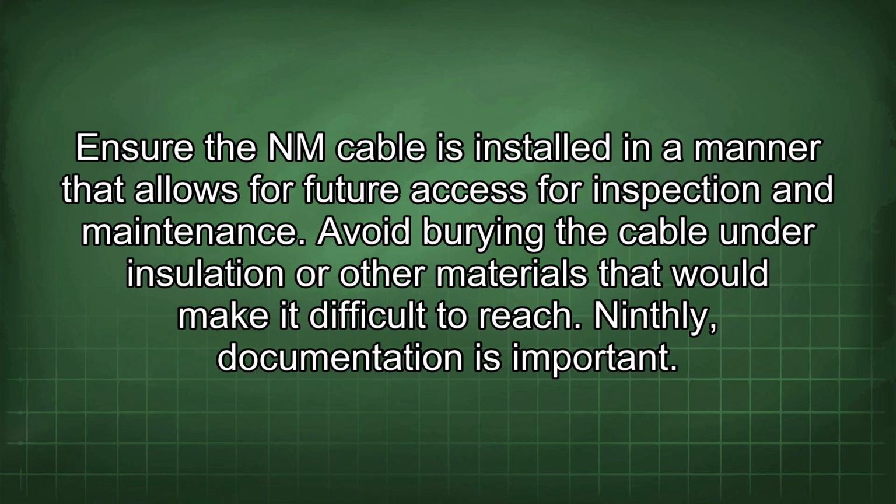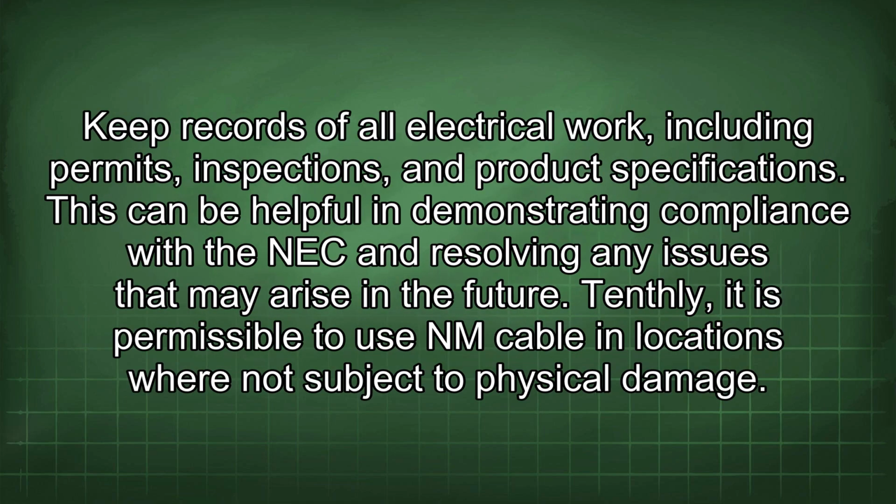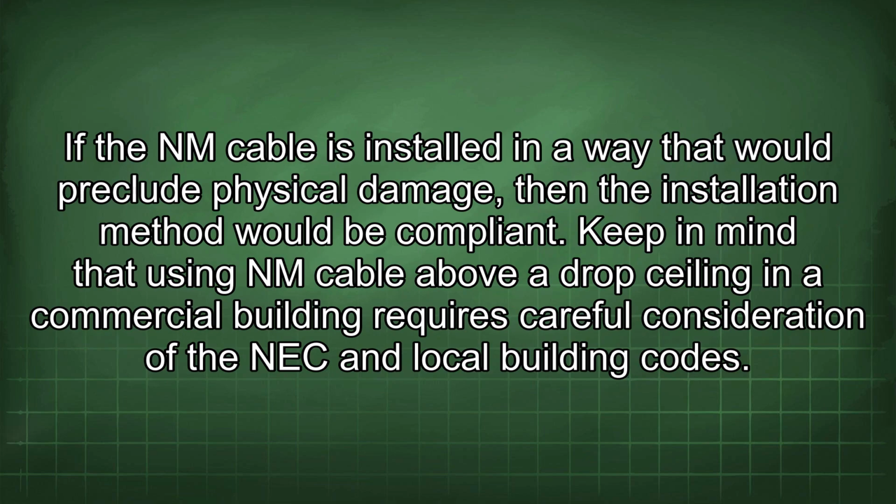Ninthly, documentation is important. Keep records of all electrical work, including permits, inspections, and product specifications. This can be helpful in demonstrating compliance with the NEC and resolving any issues that may arise in the future. Tenthly, it is permissible to use NM cable in locations where it is not subject to physical damage. If the NM cable is installed in a way that would preclude physical damage, then the installation method would be compliant.